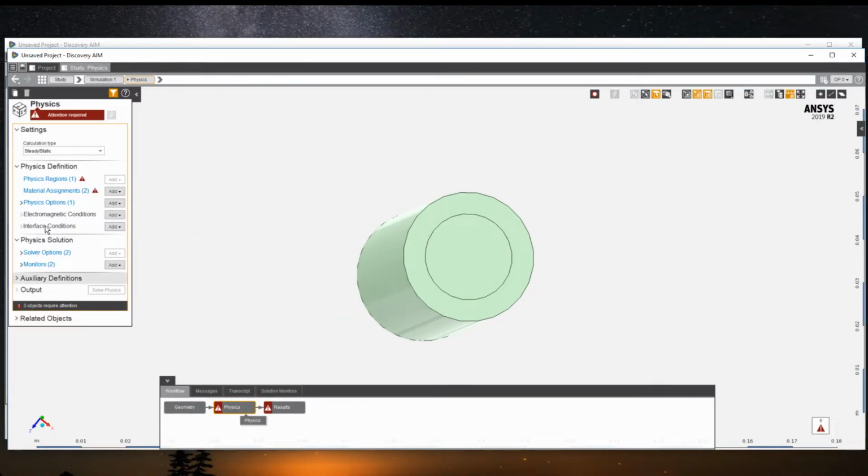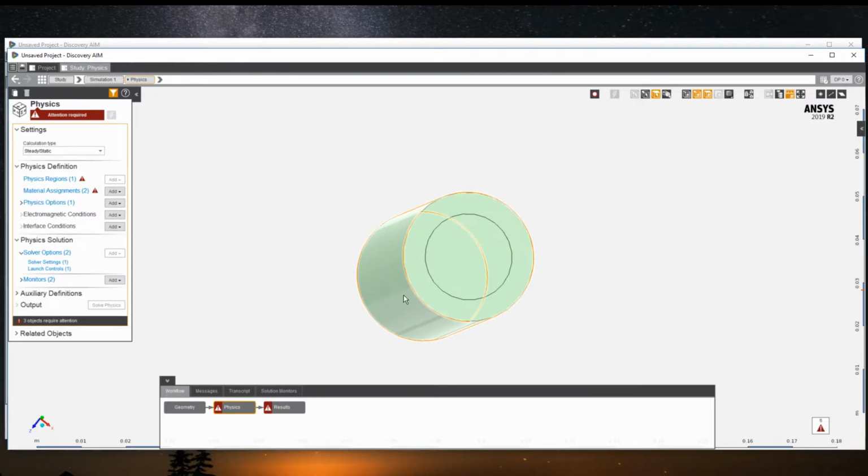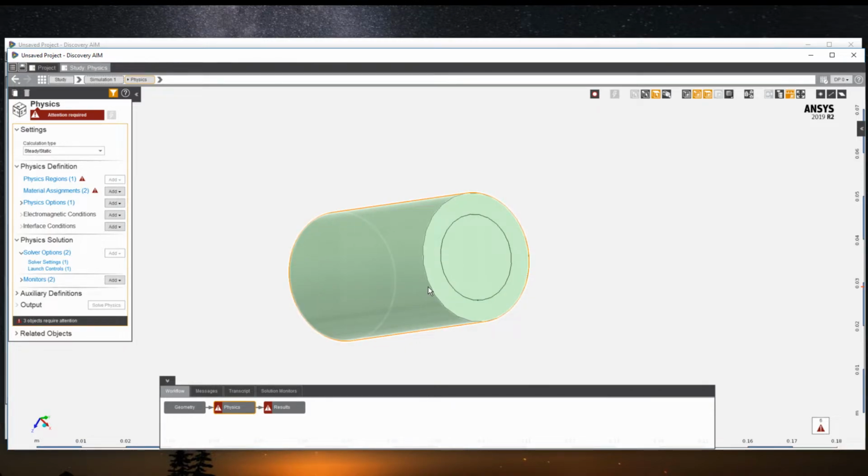So now let's go to physics. All of these settings are the same for the apply current, but I believe I chose the permanent magnet in this case, so it may not give you the options. But when you select apply current under this electromagnet, when you assign the ports, it will allow you to set how many windings for the coils.